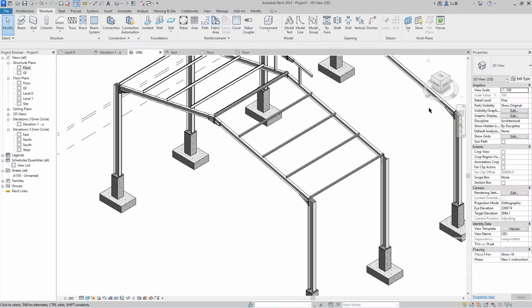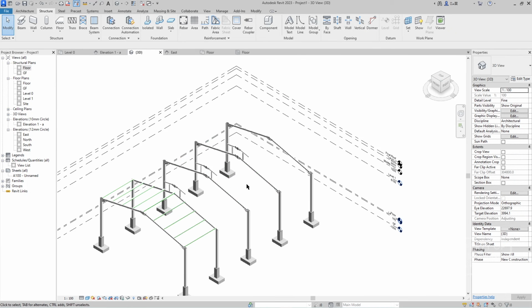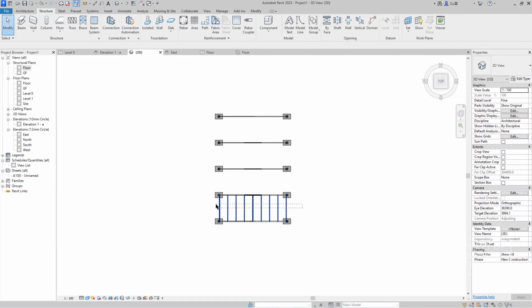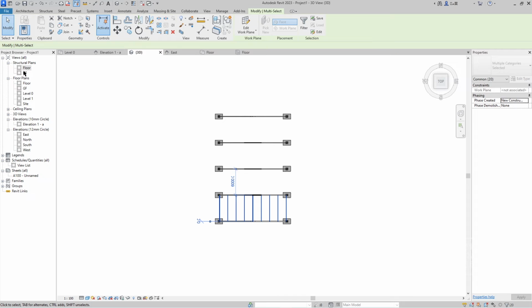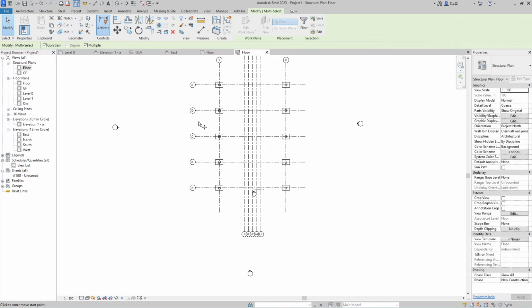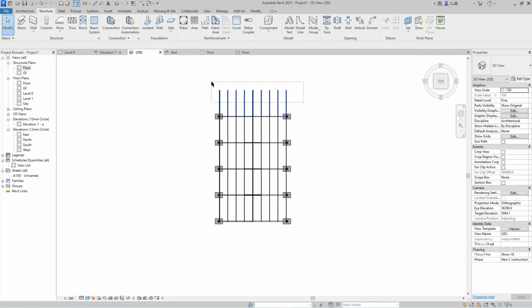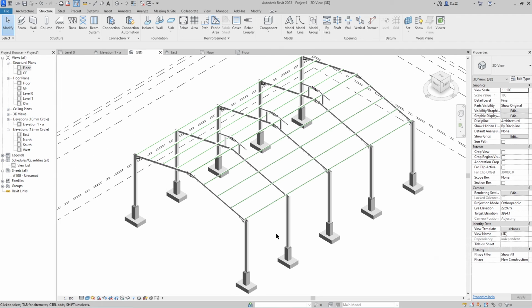The next thing you should do is copy everything here to another section. So I go to the top again, select all of the rafter, go to the floor level maybe, and type CO from this point into this point, this point, to this point, to this point. Last one. If I go back to 3D, yes, we just exceeded the limit, so delete it, and congratulations, everything is done.